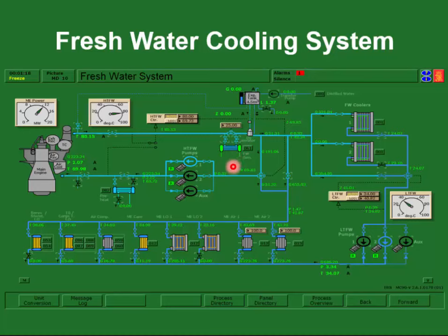One thing I want to note and talk about a little bit with you, though, is the fact that when you, as a cadet or as a third, you're going to be asked to switch these valves over. Usually what happens is you put the valve, once you get out of port, and the main engine is coming up on full line, then you will switch this. Just remember always to open the cooling water to the evaporator prior to closing the bypass, or you can shut water off to the engine while it's under load.